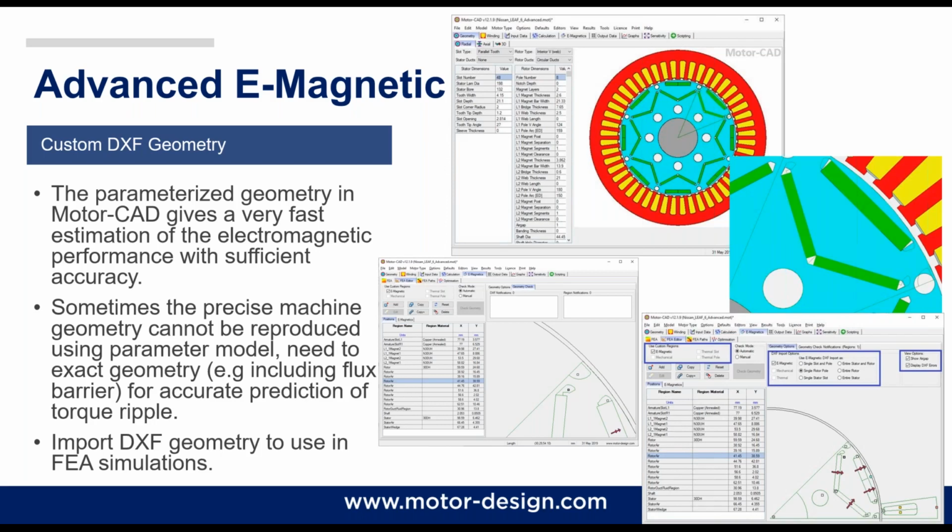It's important that the MotorCAD parameter model matches the DXF geometry as closely as possible. Air gap thickness and location is most important, since this is defined by MotorCAD geometry for the FEA simulations.